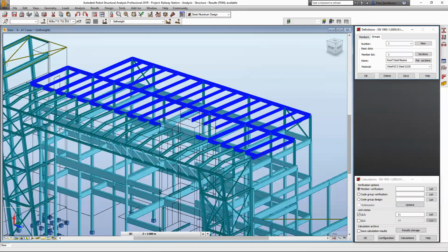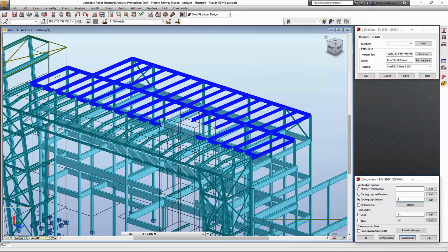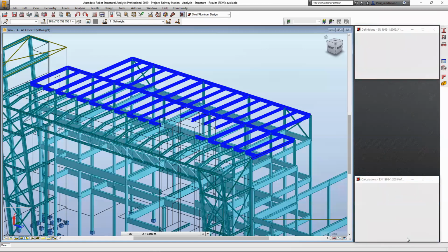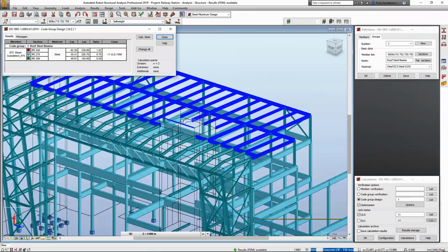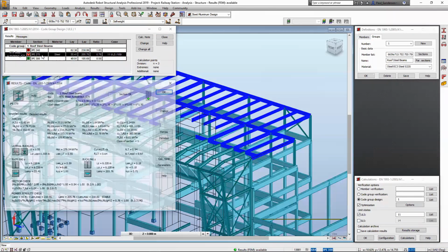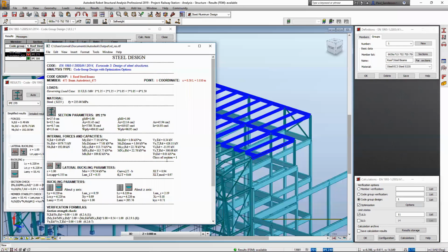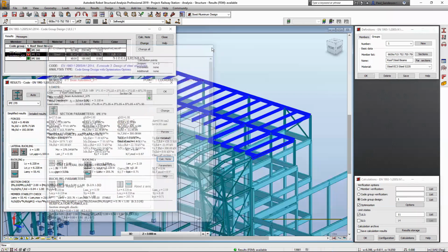So it's not just analysis; you can also start optimizing. In a case where you're looking at a structural element, like the one you are seeing currently, you can start grouping your structural members together. For example, on this particular floor, you see that the beams are likely to be the same. You just select each of them and then start optimizing. Then the product will give you the ones which are likely to perform better. It just ensures that you don't over-design or under-design in terms of the structural integrity of the model.